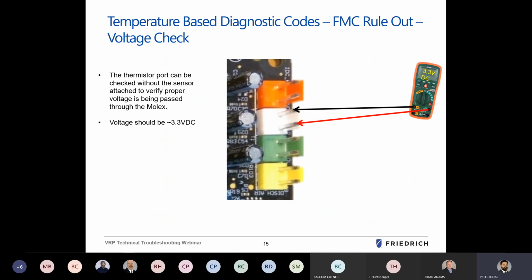Earlier this week, I troubleshot a bad sensor with a manufacturer's representative. The unit was giving a certain error code. We ohmed out the sensor, and it appeared fine. We went to the board, and it turns out the pin connector was only putting out 0.8 volts DC.